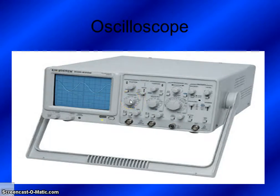So let's say it were 2 volts per division. If you look at this wave, from top to bottom, see where the trough is there, it's 2 boxes high. That means that if this were, let's say, 5 volts per division, it would be 10 volts. You got 5 and 5, so that would be 10.